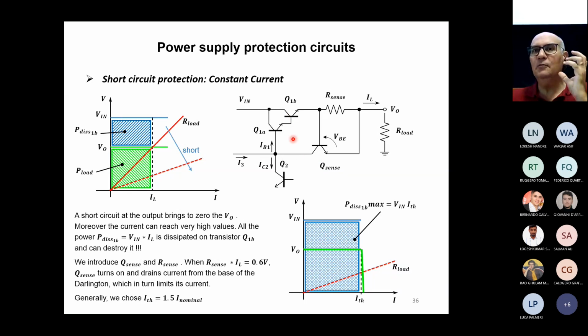It's a dynamic system where actually if this transistor reduces too much the current, we will have a voltage on our sense which will be below VB. So actually where the system stabilizes is on a point where the current passing through the transistor is basically the threshold current.